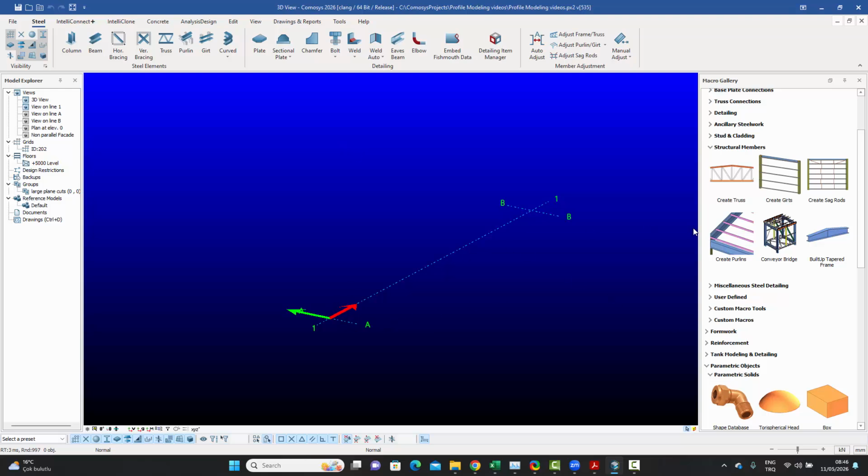So let's start by trying to enter the column. So we click on that. We select this start point. And we know that the height of the column has been given as 8 meters. So we hover over the same point and we say EZ 8,000, like that.